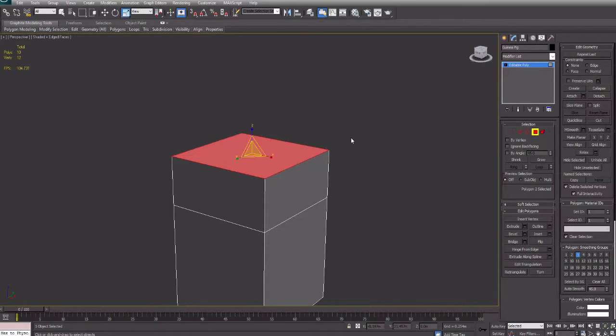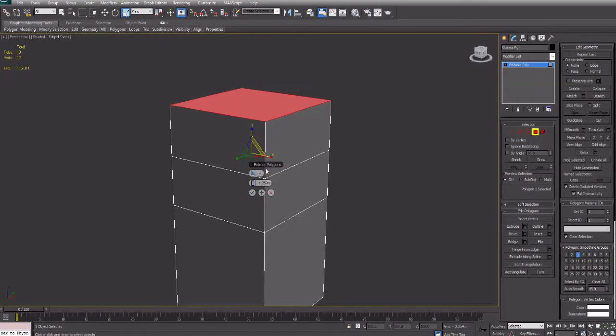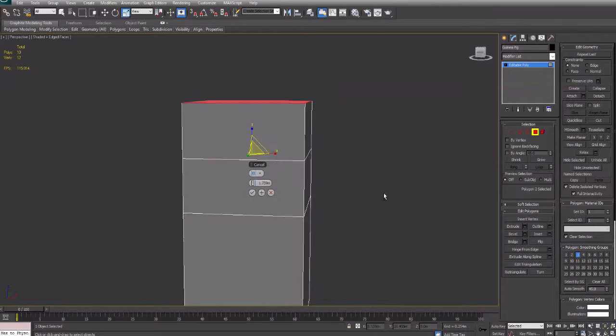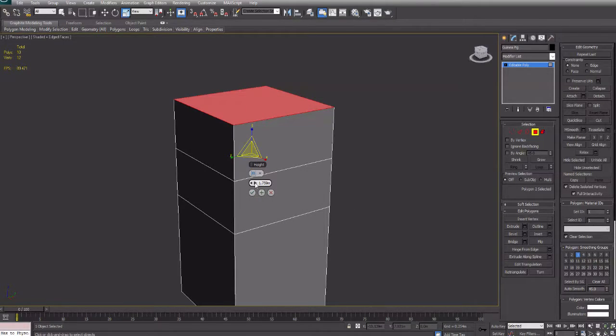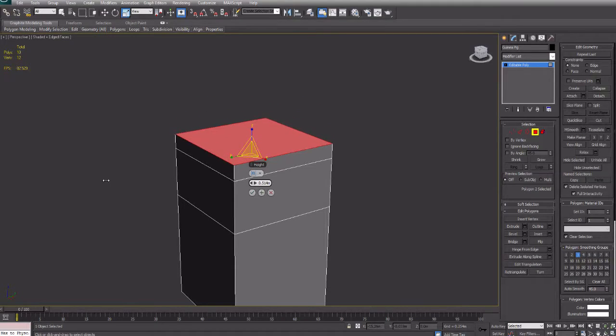Or you can do that precisely by pressing this one, the settings. Sorry about the dogs. So if you press this one, you can see this thing over here, the sliders. You can set the height here precisely. If you're doing architecture, you really must be precise with your measurements. And group, local, normal, polygon, you will see that in a bit later. So press OK if you're done.